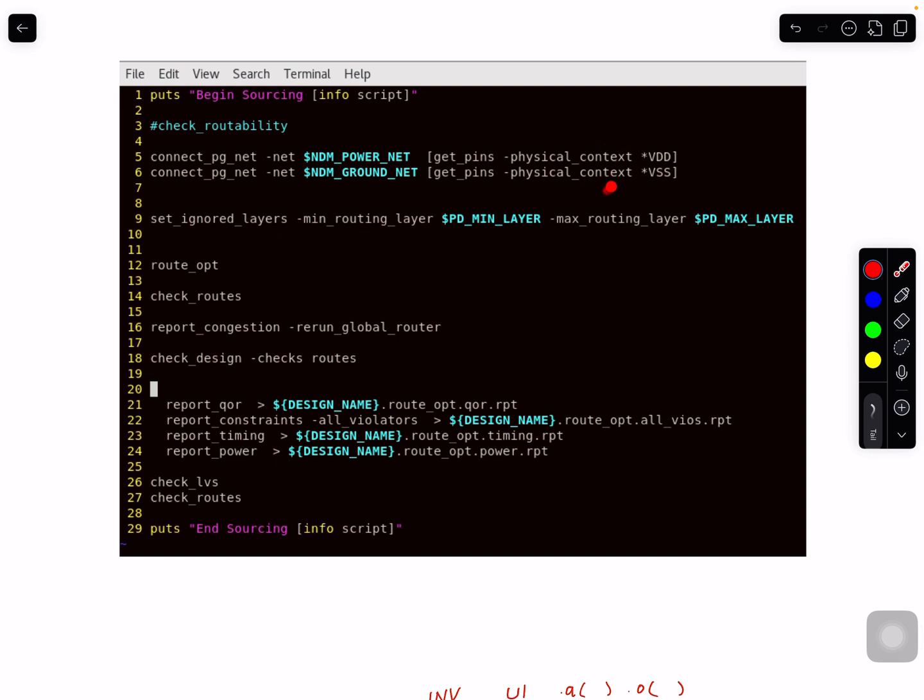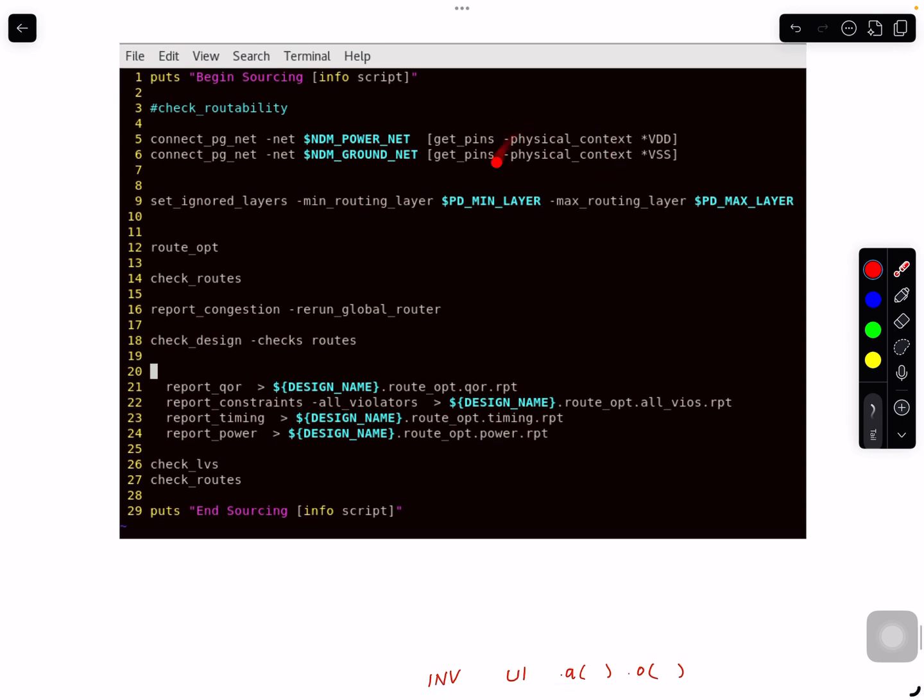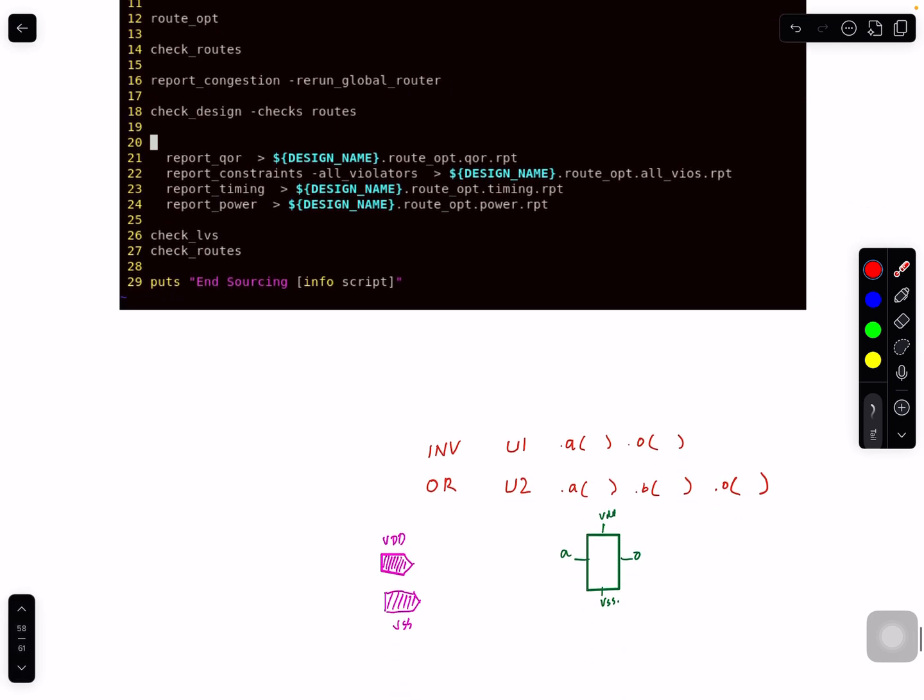Here I'm just doing it just in case. Actually, it should be in the design already, the synthesis tool should maintain it, but I was just making sure. So this pin VDD, I create at the top level my terminals. Remember the power grid that I had? So I need to logically, even when I connect this physically, all the different rings, then remember what else, a mesh, then comes the standard cell rail, and eventually I, through vias, connect these metal pins to the grid.